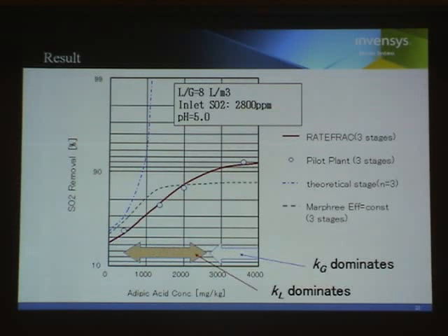And from the RateFrac calculation result, in low concentration of buffer component, it was obvious that the liquid phase mass transfer dominates these results. And when the concentration becomes higher, the gas phase mass transfer dominates the sulfur dioxide removal.